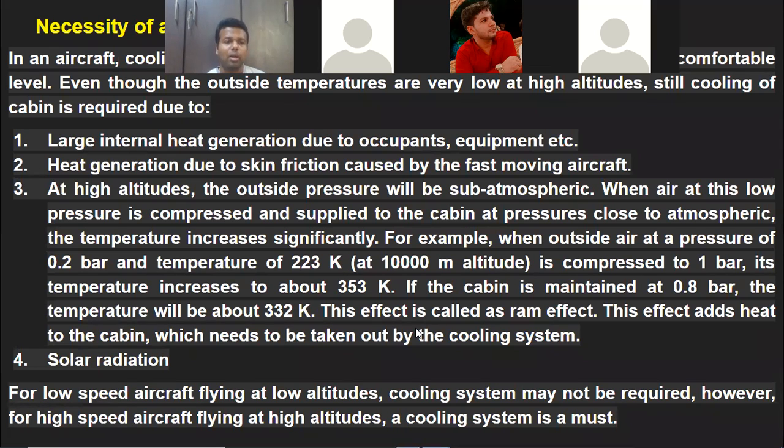A simple example: at high altitude, the outside pressure is subatmospheric. When you compress such air and supply it to the cabin, the temperature increases significantly, right? Because outside we have a very low pressure, and when you compress the air at this low pressure, what happens?